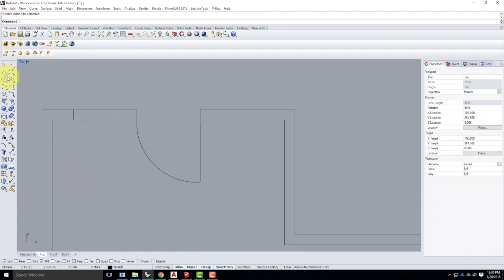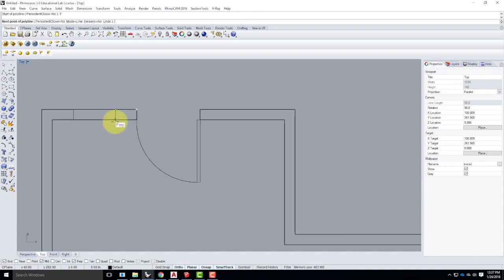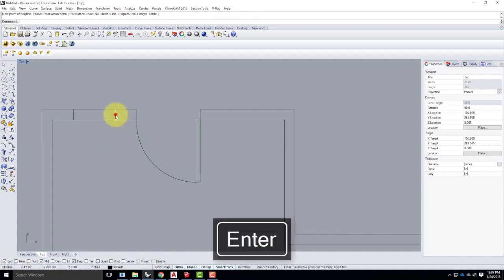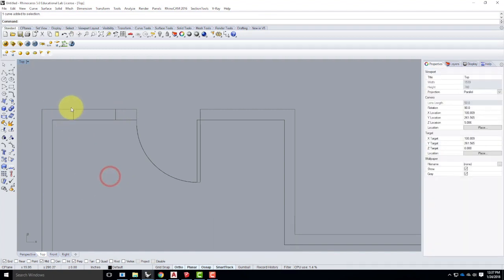I'm going to do it again for the other side. So I'll start with my line. I'll hover my mouse, again not clicking, on that corner. I get the white dot. I move to the left this time, and I'm going to type in the value. It was 1 foot from the door, so I'll type 1 foot, enter. There it is. It's 1 foot from that little blue dot, and I can draw that part of the line. So there it is, just a single line and just a single line. No other lines. Okay, that's what we're after.